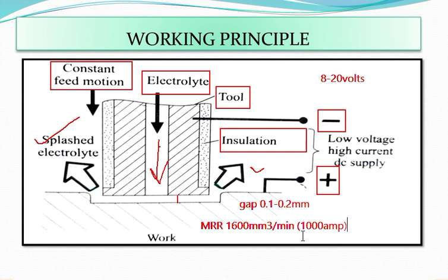When you are ejecting a high pressure fluid in the gap, then only a large force is exerted on the tool and the workpiece. Otherwise, the tool is not subjected to any forces.